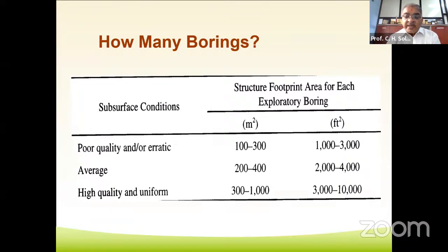How many borings will you go for in an area? Here, for the different subsurface conditions, it has been suggested that when dealing with an erratic subsurface, you may have to go for more borings, whereas when dealing with high quality and uniform soils, you may go for fewer borings.